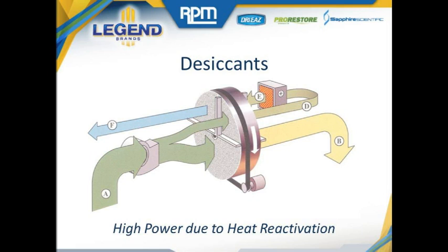The only way to compensate for this is to use exceptionally more dehumidification than would be required had a refrigerant dehumidifier been chosen initially. This overcompensation in dehumidification further exacerbates the issue with the overuse of energy during the drying process with desiccant dehumidification. In projects where evaporation rates are slow from primarily just dense materials on the structure drying project, desiccant dehumidifiers can be an ideal choice. However, whenever highly porous materials are present or high degrees of saturation, desiccant dehumidifiers do not provide the efficiency necessary to properly manage the restoration project.